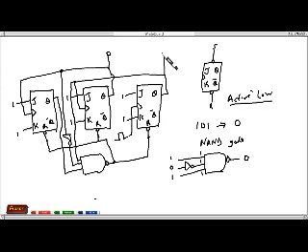So this will be our outputs, which we can connect to a display section. And through this, we're able to implement a mod 5. This will be a mod 5 asynchronous counter, counting 0 to 4. 5 digits, 0 to 4, and becomes a mod 5 asynchronous counter.